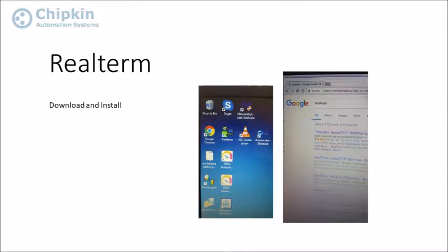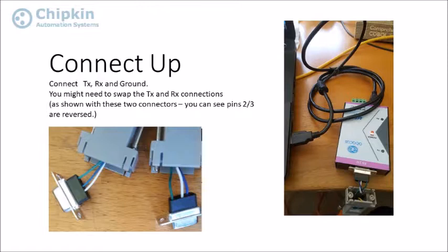Now it's time to connect to the device that's transmitting data. Let me tell you what I mean by that. We're listening to a 232 port. We're not generating data. We've got to get the data from the device. If that device is a server device, a slave, you're not going to get anything out of it because it's waiting for you to send it a message before it responds. So for the purposes of this video, I am assuming that the device we're going to connect to is transmitting data to us, and then we're going to capture that data. In other words, it's a master if you're talking Modbus or something like that.